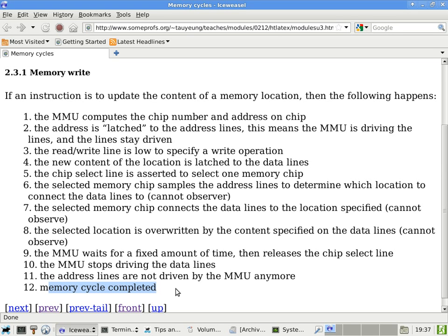Yep. So this is actually what a modern chip is doing at like 1300 megahertz. It's doing that many times a second. Not quite. That's a good question. The question is, if you buy DDR3 memory these days, they can be specified to go, I think, all the way up to 1600 megahertz, which is actually the wrong unit, because it should be called 1600 transfers per second. That's the proper term. No, that's not how it works.